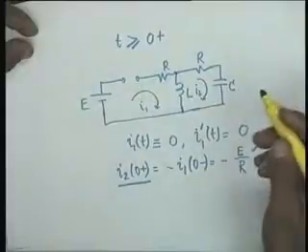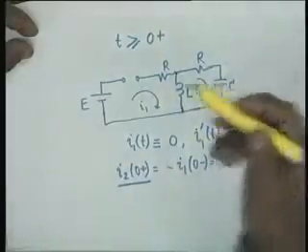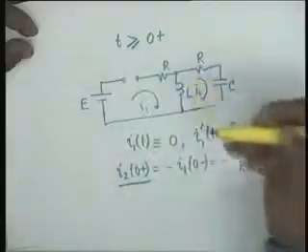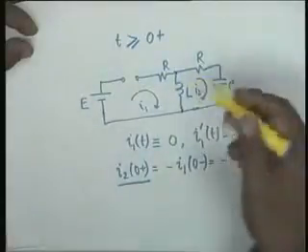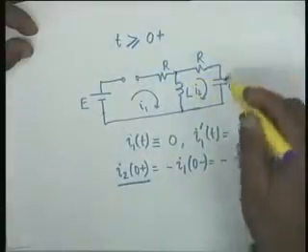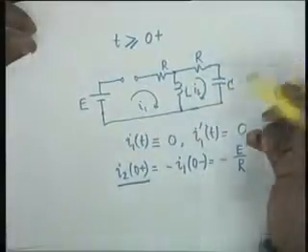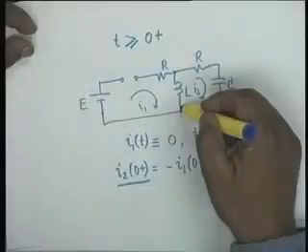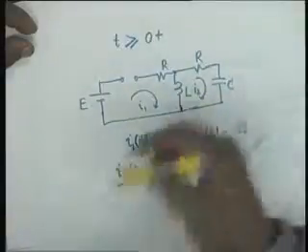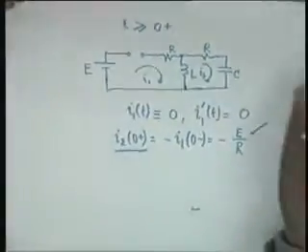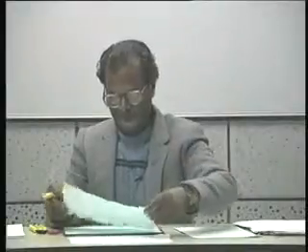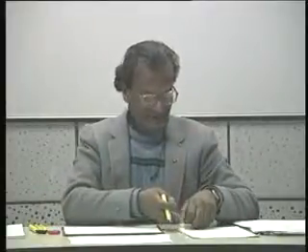To start with is a different story. That is, at t equal to minus infinity, the battery starts charging. But in the steady state, even if the capacitor had acquired a charge, it would have discharged, because it finds a very easy path here, short circuit. What we are considering is the steady state condition. All right. Okay, that takes care of 5.3.